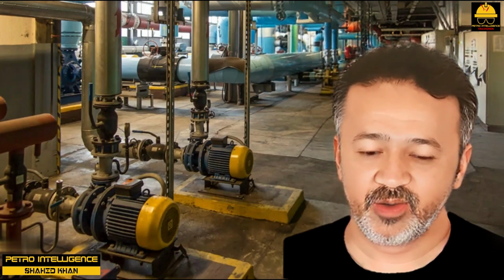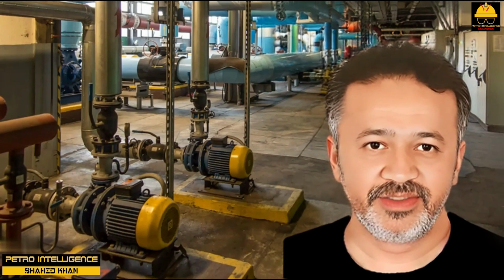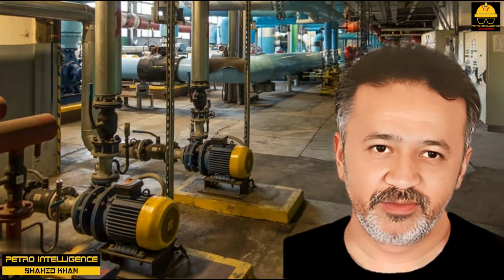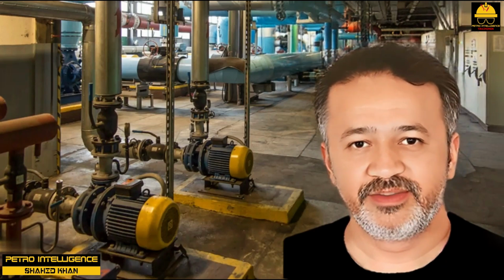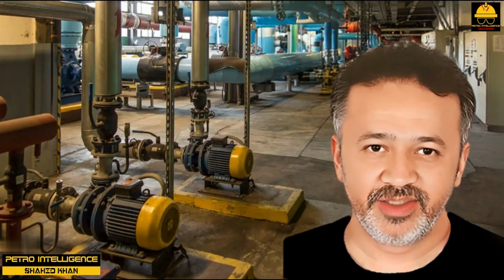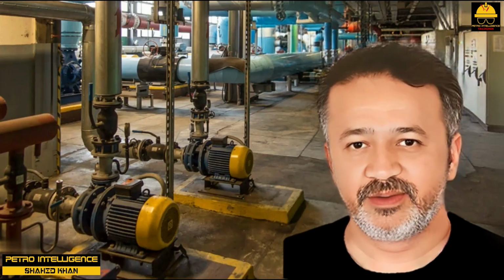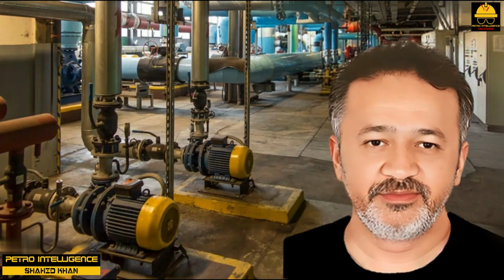Today we will discuss centrifugal pump drivers, electric motors and steam turbines and their limits. There are three types of limits on centrifugal pumps. Impeller limit. This was the subject of our lecture on centrifugal pumps fundamentals. Sometimes this is called a pump limit.